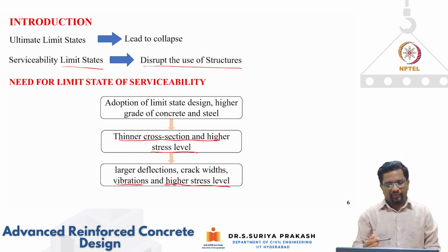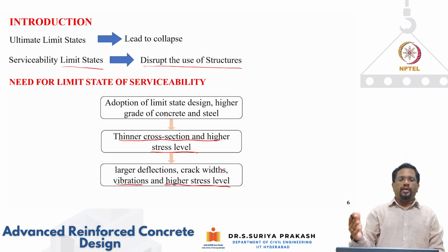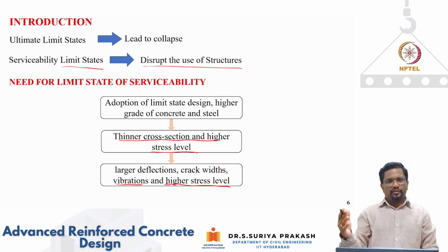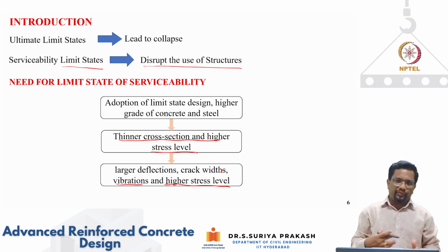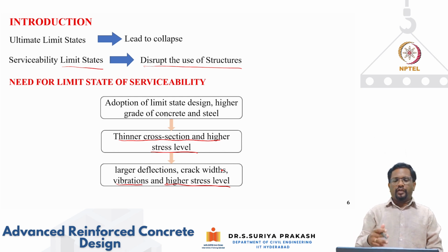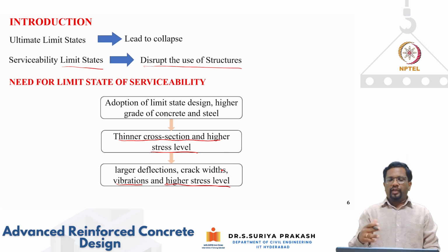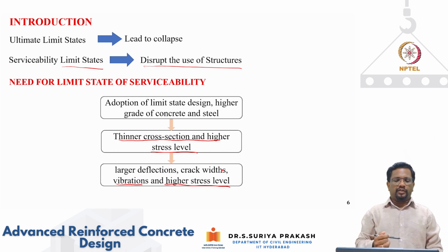So it's not that limit state practice is not good; we have come up with a more efficient design philosophy, and we are also using high strength material. If you are not careful, then you may violate the deflection and crack width requirements.